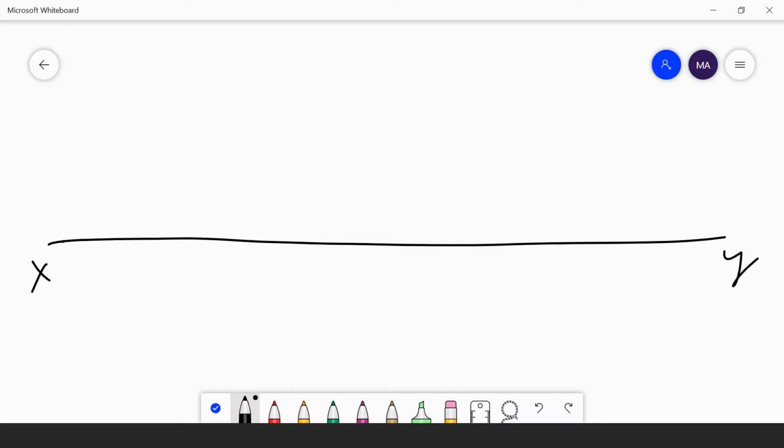Here we are considering the reference line XY. He is saying that the pentagon is resting on its side, so I am drawing the pentagon such that it rests on the side. This will be A dash, B dash. Then I am taking 108 degrees as the angle here, and here also 108 degrees. I told you yesterday the interior angle of a pentagon is 108 degrees.